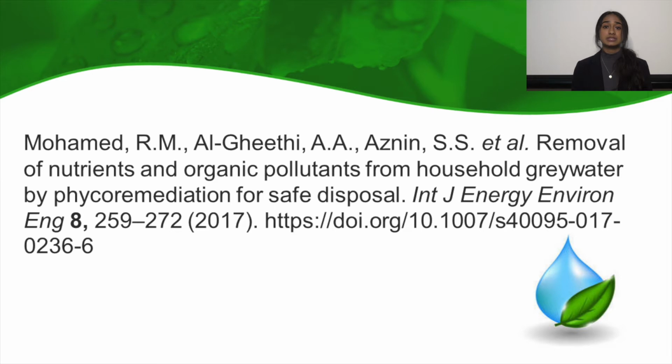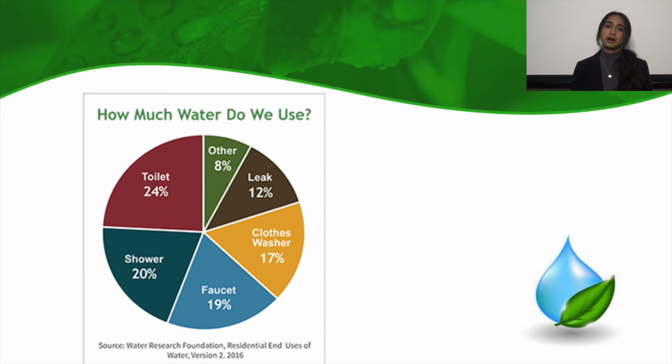Phycoremediation with indigenous microalgae is often used for gray water treatment, and the process requires a treatment time of a couple weeks. The gray water purification in my research is purely for toilet flushing. Based on the amount of water generated in the shower and daily water requirement for toilet flushing, there is a very good balance between the two to notice any overflow of the gray water tank.